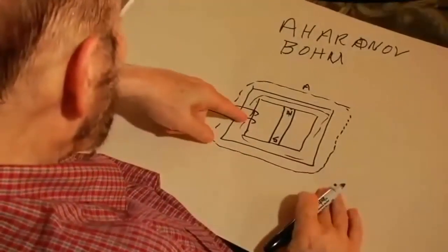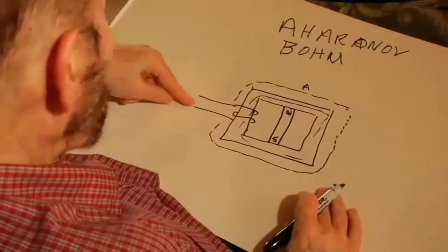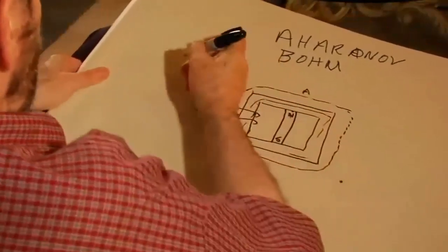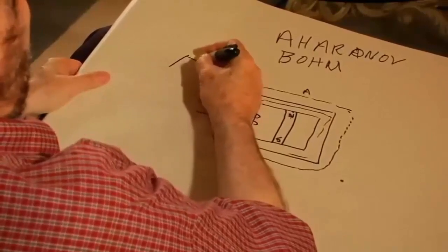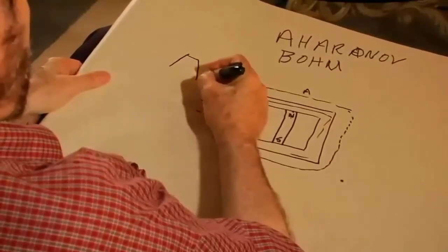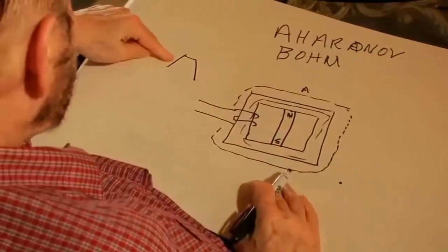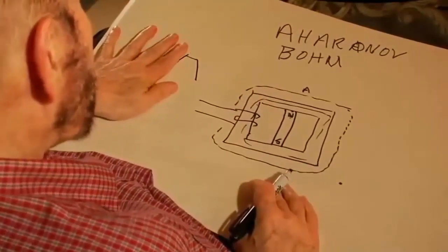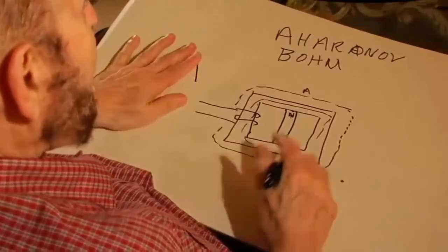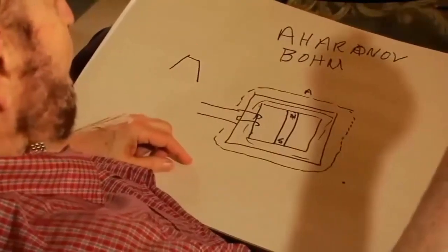And every time I perturb the core, like with my input coil, I put in, clever devil that we are, we put in pulses, sharp rise time and sharp decay time. If I want to get a little bigger E fields, I make a sharper rise time and a sharper decay time. I get an E field one direction one time and the other.